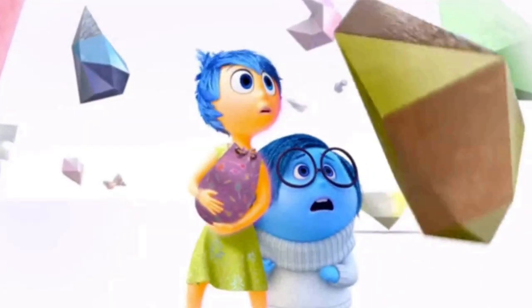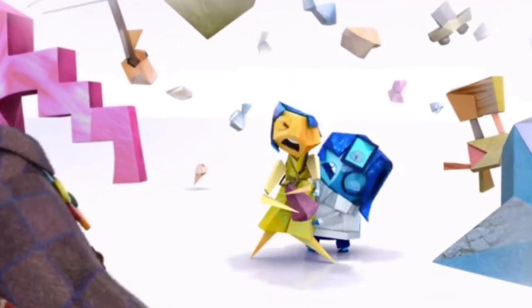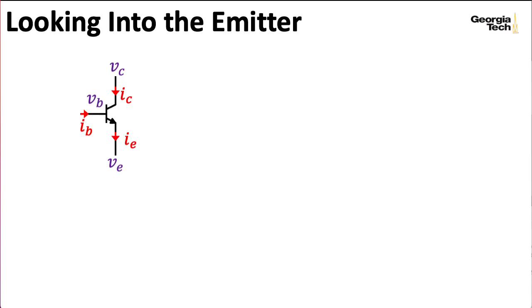BJT. Now, I realize that all of this material seems fairly abstract and esoteric, but trust me, it will pay tremendous dividends in terms of simplifying the kinds of analysis we can do when looking at various amplifier structures. As in the previous couple of lectures, the BJT symbol here doesn't represent a BJT in its full glory. It specifically represents a small signal model. So according to our convention, all of the voltages and the currents here are indicated with lowercase letters.